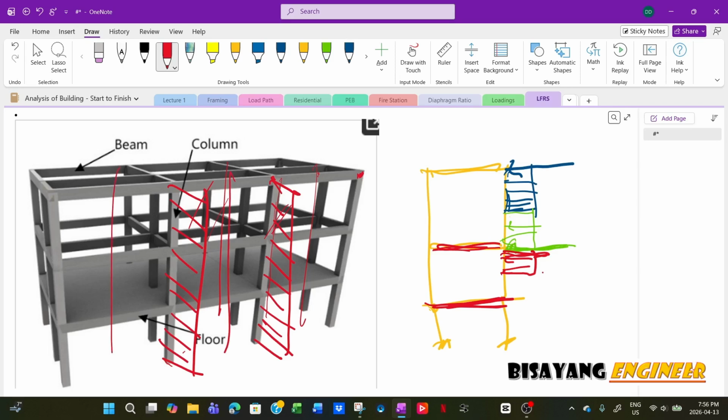Now, this one is only correct if you have a girt, horizontal, so that half of that will transfer to the column directly, not to the beam. But if it's the other way around, if you have vertical studs, then half of that load will be transferred to the beam instead of the column.